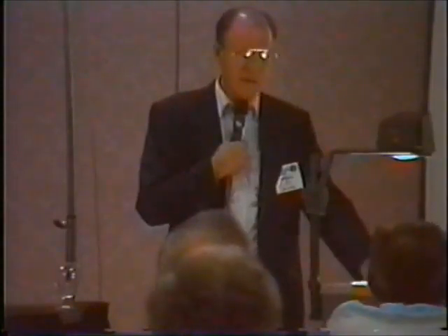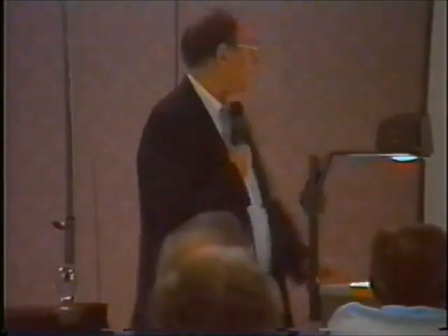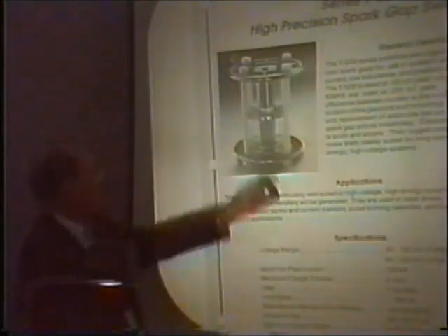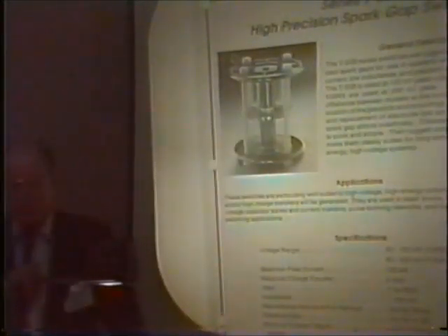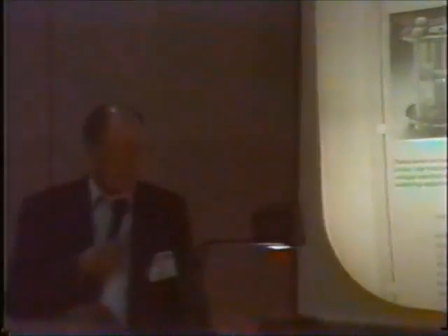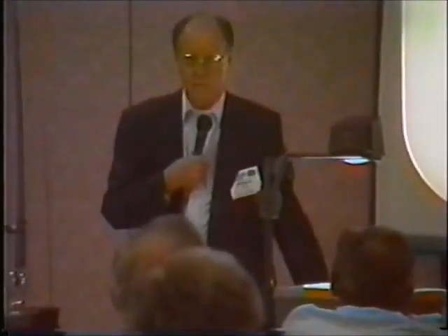And there are other kinds of spark gaps. This is one of the types we're talking about. See the spacing between there and there. It also has this center piece, which prevents an overflow if you reach proportions which are dangerous to your spark gap. That partially unloads it so that it doesn't destroy your spark gap.